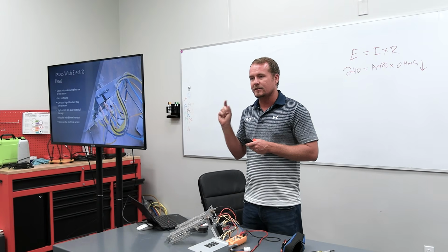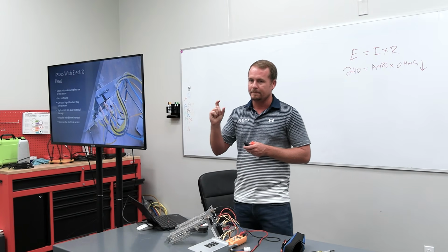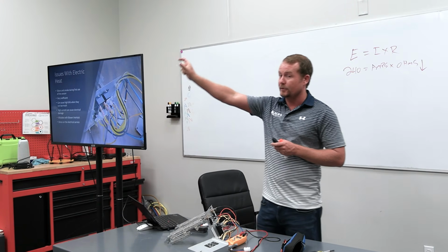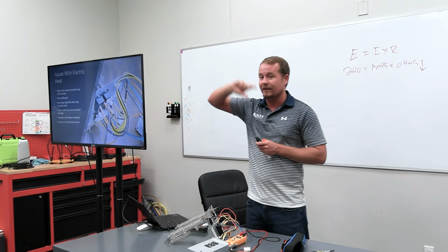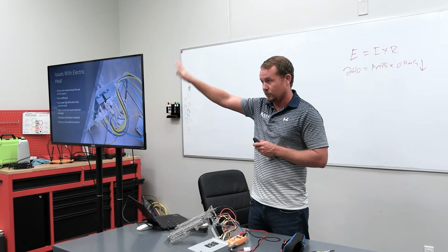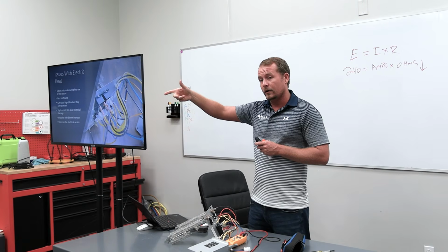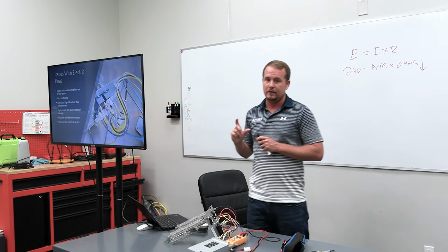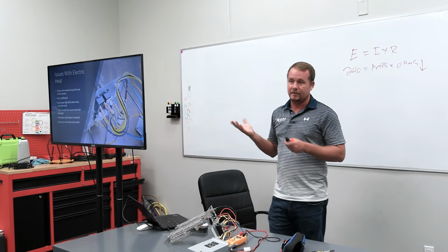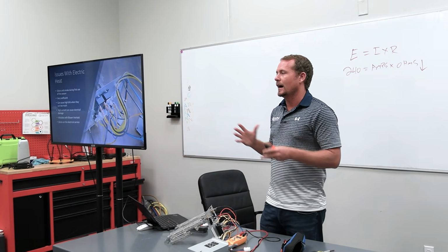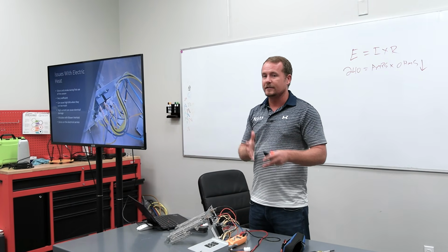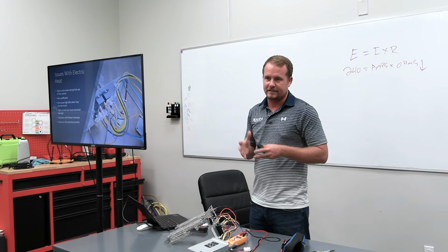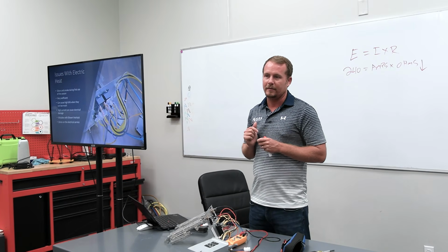Problem with that is some thermostats have built in an algorithm that uses outdoor temperature, like the modern fancy ones. It won't even allow them to come on if the outdoor temperature is high enough, and we're going to talk about that. Or they have a time function, so it has to run a certain amount of time before it's going to let it come on. So you could just be sitting there a long time, depending on the settings. So probably not your best way. Going into the installer setup or your installer service setup and just driving on that mode is probably going to be a better way.